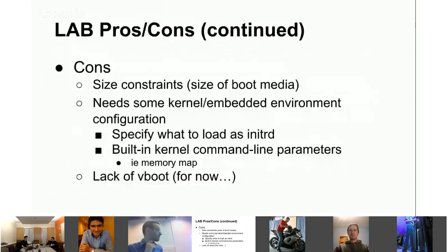Of course, the biggest drawback is the size. Linux is big. Having a nice full-featured embedded development environment is going to be pretty big too. So I like to cheat, and I have one of our lab technicians solder a nice big 8 meg or 16 meg SPI ROM on boards that I'm messing around with, or I just have them put a socket on it, and they're very good at doing that. So that helps a lot.